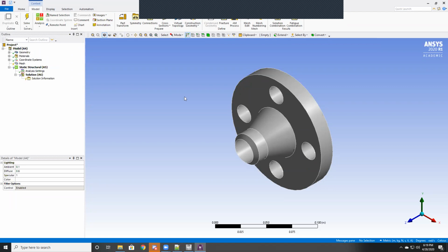And related to that, because the quality of the mesh is so important, never, ever put people in a dangerous situation with a part if you haven't tested it in actuality. Don't trust an Ansys sim. Always perform tests to qualify your parts and verify your models. That's the number one reason for testing. Once you've done a simulation on one kind of part and verified it, then you can have a little more trust, but always test and verify the models and make sure you're not missing something.